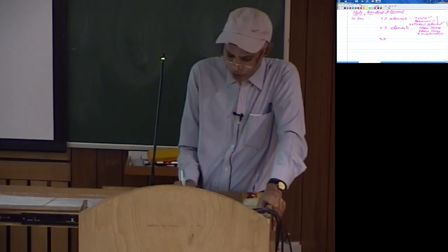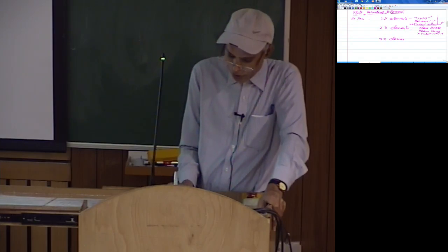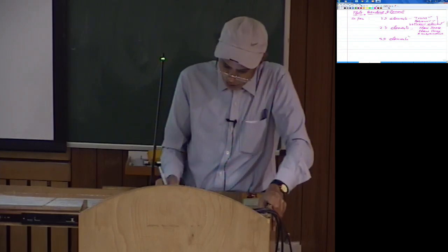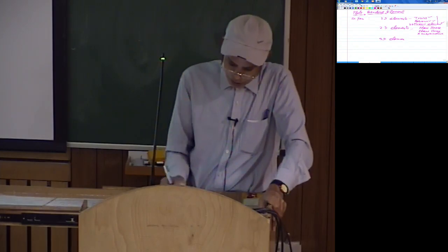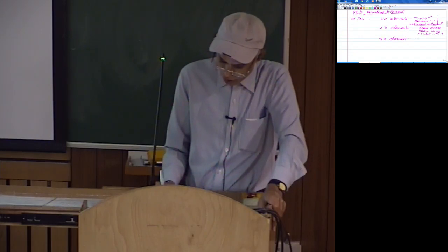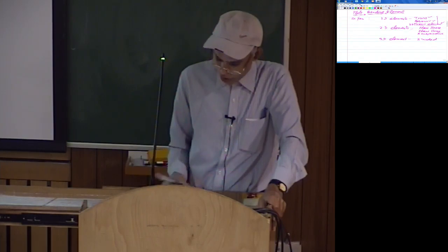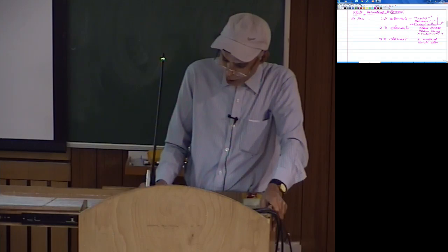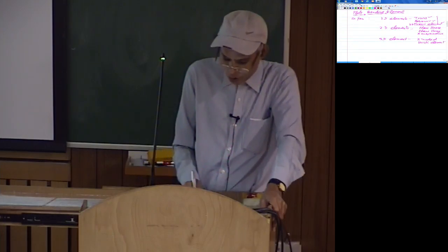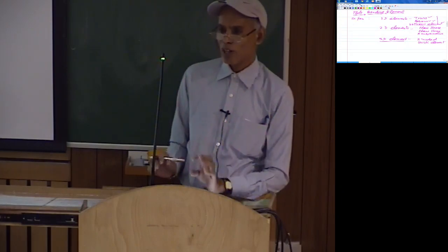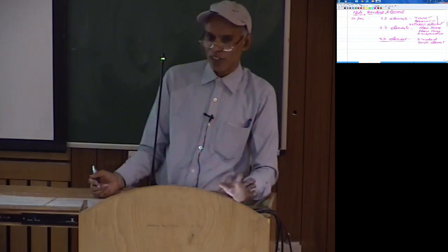Then we discussed 3D. Of course we discussed only one element, and I said that you can degenerate this to tetrahedra. So here we discussed the 8-noded brick element. You can also similarly formulate, say, a 20-noded brick element. So ideally all problems can be modeled using a 3D element, because in this you are not making any approximation about no variation of the displacement along the 3 directions.